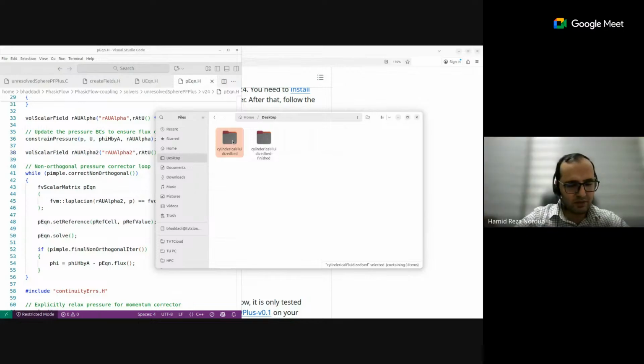Yeah, for the CFD, you're absolutely right. And for the DEM, of course, we covered it in the previous sessions. We go for the critical time step, we calculate it, and then we select a right resolution for the time step. And based on the resolution that we require for the time step, we select the time step, and that's all for DEM. But for the coupling, a very important parameter here is